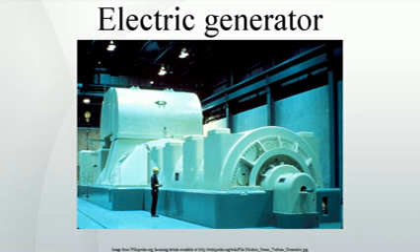Field, the magnetic field component of an electrical machine. The magnetic field of the dynamo or alternator can be provided by either electromagnets or permanent magnets mounted on either the rotor or the stator. Because power transferred into the field circuit is much less than in the armature circuit, AC generators nearly always have the field winding on the rotor and the stator as the armature winding. Only a small amount of field current must be transferred to the moving rotor, using slip rings.